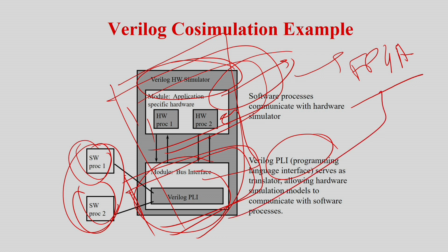So nowadays people are actually taking this environment. That is why FPGAs have become a very key role player in integrated environment based test. Instead of simulating the hardware, they develop the hardware fully, but I cannot fabricate it because it takes a long time. You download it to the FPGA, and basically you download your software onto the FPGA, which is called emulation, not simulation, and then you can see whether everything works. Still, it's good, but not as good as a co-simulation environment.